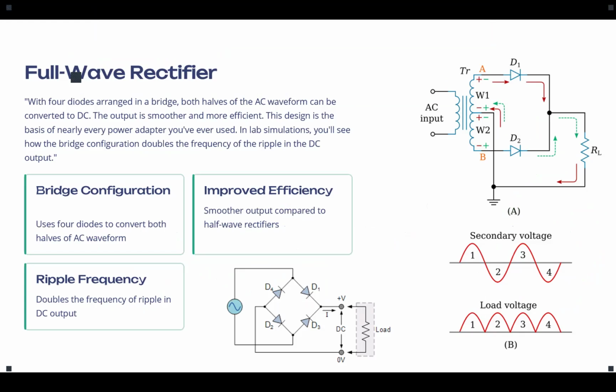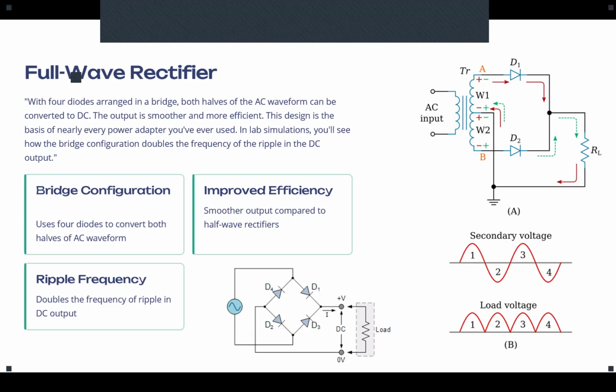Besides the half-wave rectifier, we have another type of rectifier, which we call a full-wave rectifier. For that one, we use either 2 diodes or 4 diodes based on our circuit. As you can see, in the full-wave rectifier we don't cut the negative half cycle.